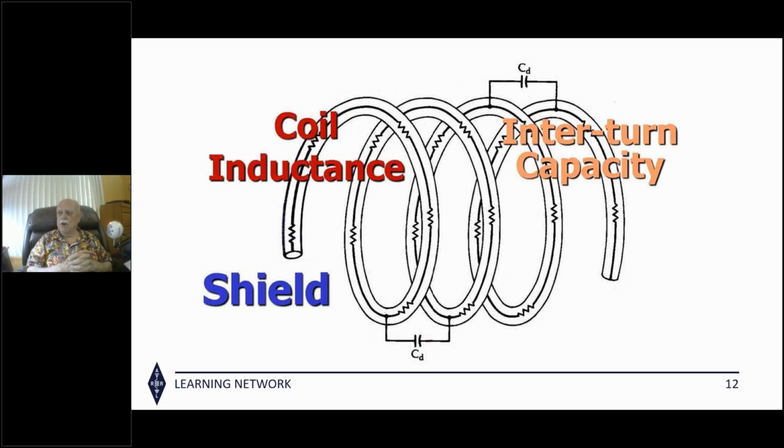But of course, the 4-to-1 Balun at the feed point will indeed help match this antenna on several bands. So it's a very nice setup. But there's very likely still to be some common mode transition occurring. The Balun may take care of it, depends on the design of it. But my personal recommendation is use both of them.